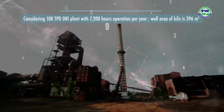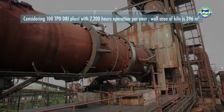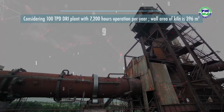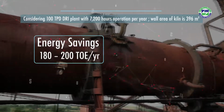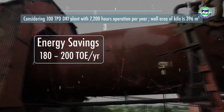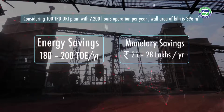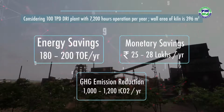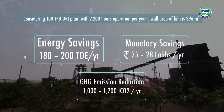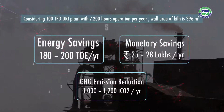Considering a 100 tons per day DRI unit operating for 7,200 hours per year with a total surface area of 396 square meters, adoption of mullite-based lining will lead to a saving of 180 to 200 tons of oil equivalent of energy, monetary savings of rupees 25 to 28 lakhs, and greenhouse gas emission reduction of 1,000 to 1,200 tons of carbon dioxide emissions on an annual basis in a unit.